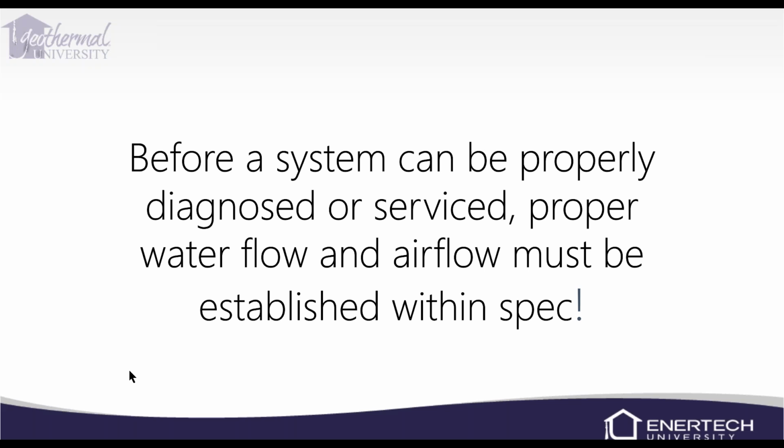Airflow is pretty simple. We have an ECM board in our forced air units, and you can count the blinks and it'll tell you the CFM. If you got an older unit and it doesn't have a CFM light, for one, you can usually hear the fan running and you can feel airflow coming out of the registers. So you kind of know you've got airflow.